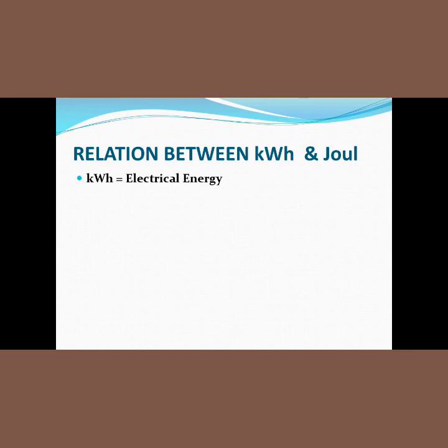Well, kilowatt hour, which is actually some amount of electrical energy, must have the same dimension as that of joule. Then 1 kilowatt hour is equal to 1000 watt, if you debit the term kilo, multiplied by 3600 seconds, if hour is replaced by second.